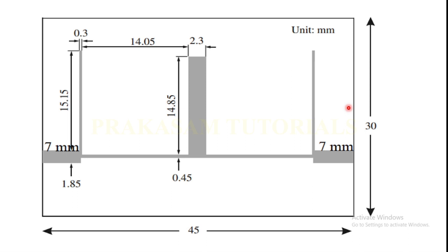So this is the layout of a wideband microstrip bandstop filter. This design is based on the 3-pole Chebyshev low-pass prototype filter with a passband ripple of 0.05 decibel.